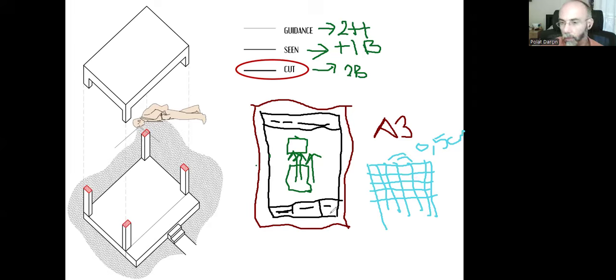And if you prefer a white paper, then please use set squares and T-squares and do the measurement, because we are going to do a scale drawing and the scale will be 1 over 50. If you prefer square paper, then no need for ruler, no need for measurement. You can just count the squares. Two squares will be 1 centimeter, and you can have a scaled freehand drawing.